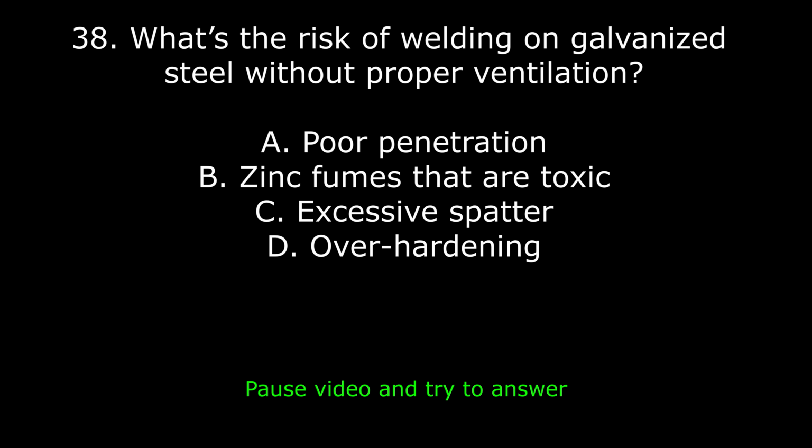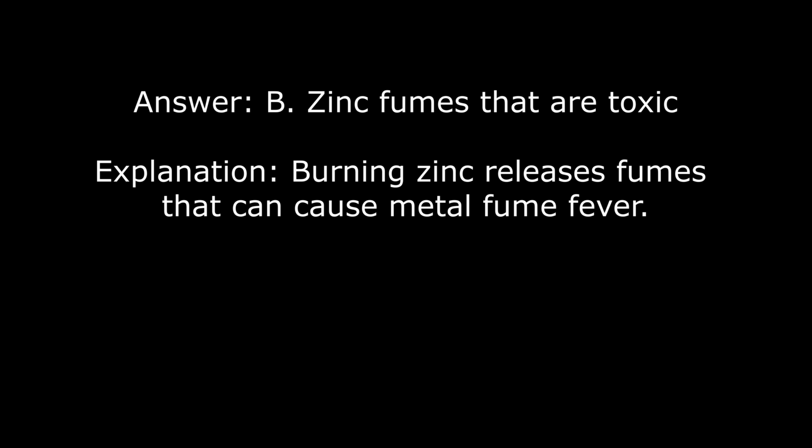38. What's the risk of welding on galvanized steel without proper ventilation? A. Poor penetration. B. Zinc fumes that are toxic. C. Excessive spatter. D. Over-hardening. Answer: B. Zinc fumes that are toxic. Explanation: burning zinc releases fumes that can cause metal fume fever.